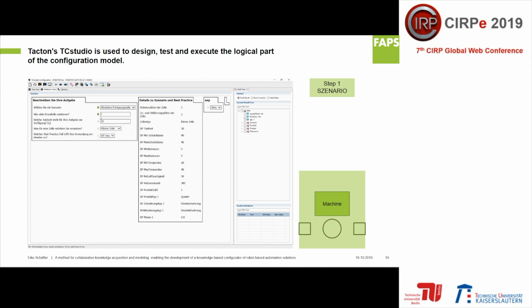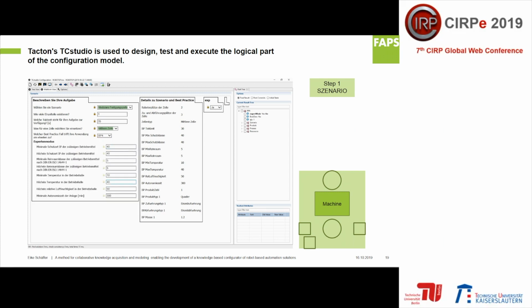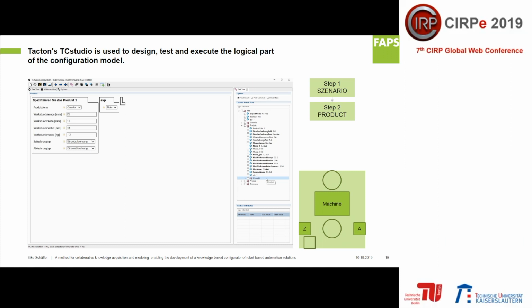In the sixth step, topology elements and their attributes' data schema are transferred into the specific configuration language. Based on these, the constraints from the fourth step are added to the model referring to the element's attribute. The constraints are translated into machine-readable language given by the selected constraint-based configuration framework. For this process, the Tecton configurator and engine was used. In the seventh step, concrete components such as specific robots or grippers are instantiated based on the data schema. In doing so, the components must be transferred to a generic manufacturer-independent description.